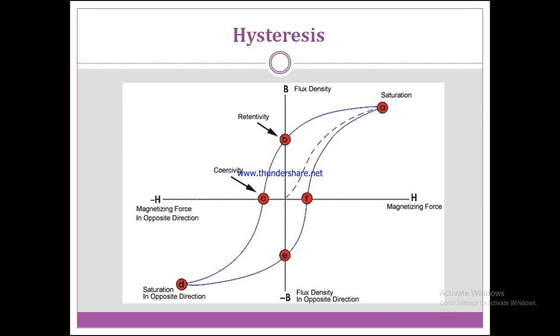Now again, increase the current in the negative direction in suitable steps to plot the points. And finally, the fourth step: decrease the negative current to 0 and plot the points. Now if we follow this procedure, we get a particular hysteresis loop along with its direction.